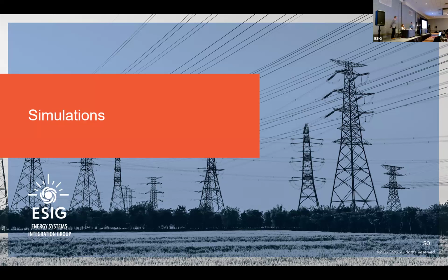At a high level, I think you need to do a little bit of both. What we're seeing now, as people start working on defining specifications for grid forming inverters, is a little bit of that. People take parts of the system, say a weaker part of the grid, model it in EMT, and test what kind of capabilities from the inverter help to solve certain issues, and that feeds back into specifications for grid forming inverters.